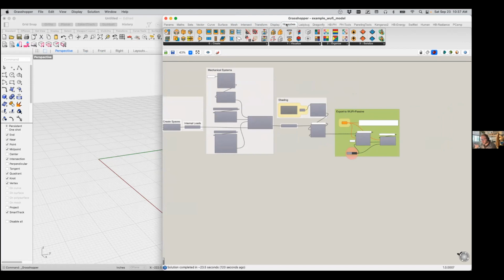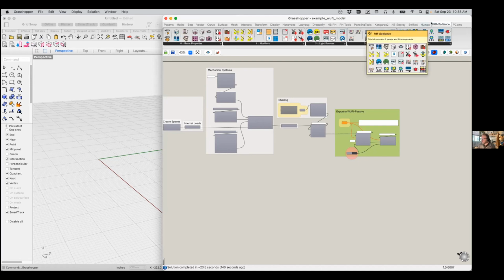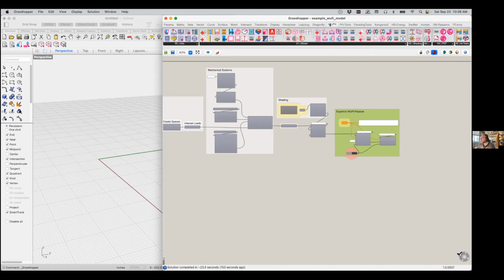Remember, honeybee is responsible for geometry creation and visualizations. I have another one over here, which is labeled Honeybee Energy. This would be the toolkit responsible for detailed hourly energy consumption, as well as thermal comfort, and limited daylighting assessment as well. We have our Honeybee Radiance, which is the toolkit dedicated to daylight simulation. And then, as I said, we have our new Honeybee pH toolkit here, which is responsible for our passive house modeling in order to assess our annual energy consumption.